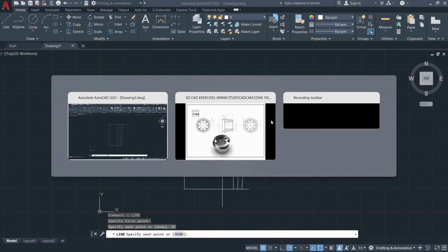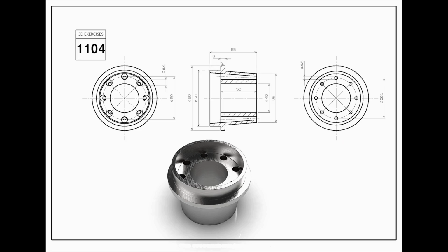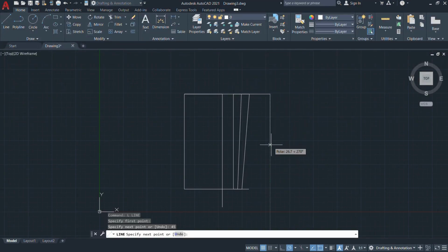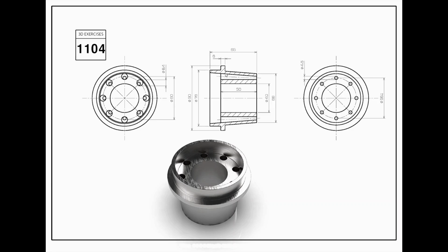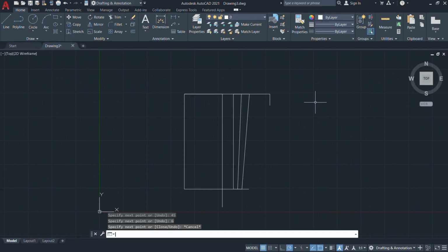And draw one vertical line. It is a length of 6 mm. So mention 6 mm. Next, we can draw a horizontal line. Before that, we need to position where it is exactly placed. So, again, I am going to choose a line profile from the center point.